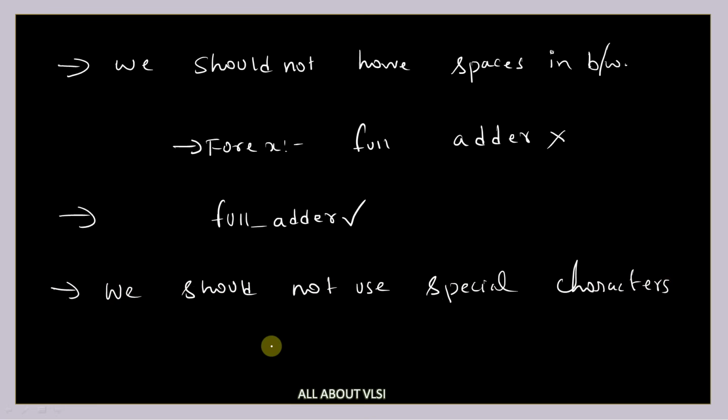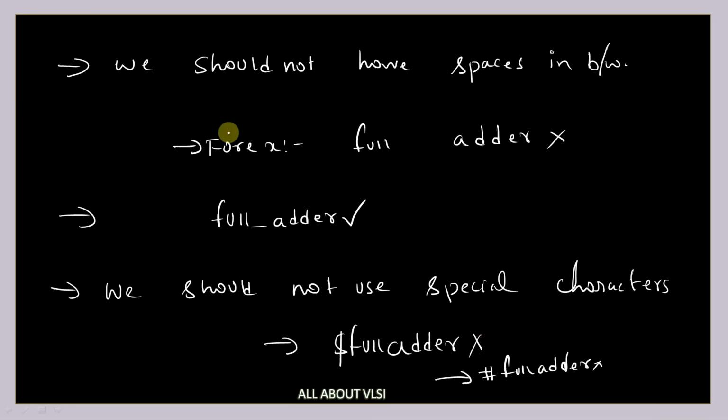For example, $full_adder is wrong. #full_adder is wrong. And you should also not use any keywords like reg, wire, module, or integer as your module name. These are all keywords. You cannot use them as your module names.